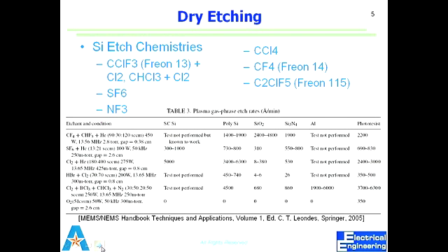Use a different recipe, okay? Or I can leave my photoresist there once I do my silicon dioxide etch with BHF, right? Because if I go further down, what is the etch rate of photoresist? Yeah, it's higher than silicon dioxide, but it's about half of silicon, right?